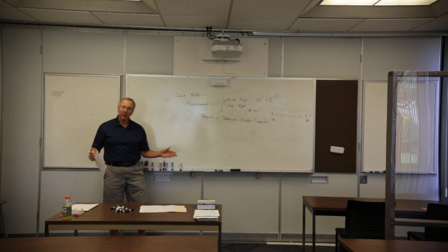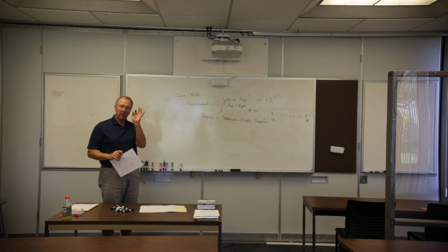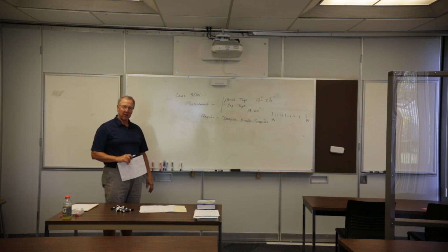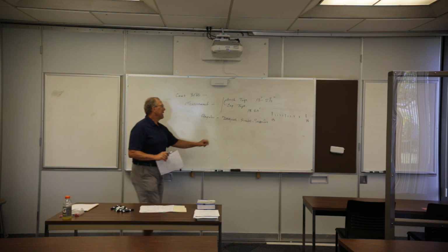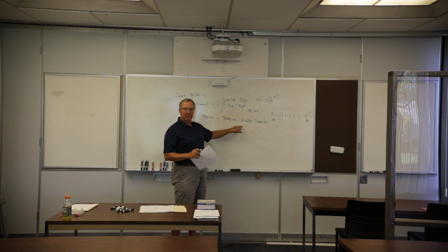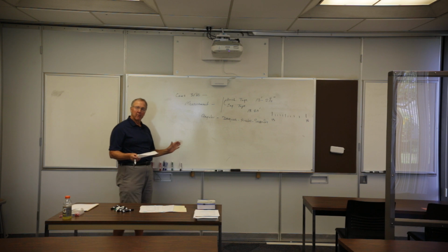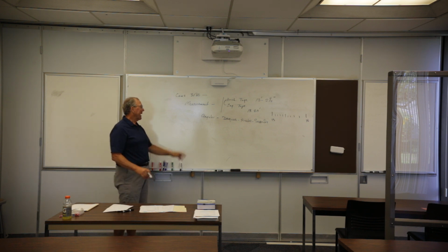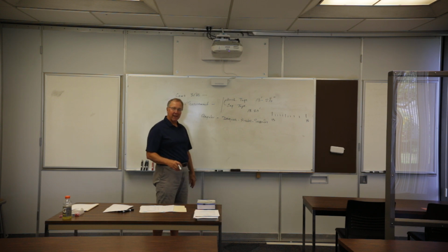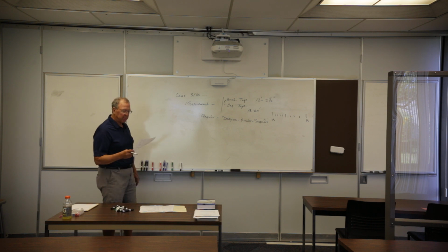A circle is divided into 360 degrees. A degree, 1 unit, is divided into 60 minutes. A minute, 1 unit, is divided into 60 seconds. So now you've got a base 12 system here, a base 10 system here, a base 60 system here. We can either have degrees, minutes, seconds, or we can have decimal of a degree. You've got to be able to go back and forth. If you try to add degrees, minutes, seconds, it's harder than adding a decimal. So you've got to be able to get angular measurements, add them, and do whatever you need to do to make them work properly.